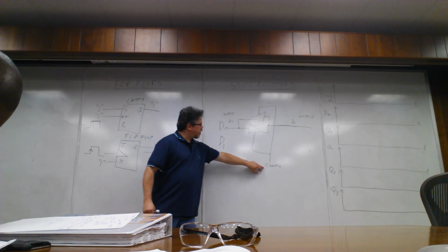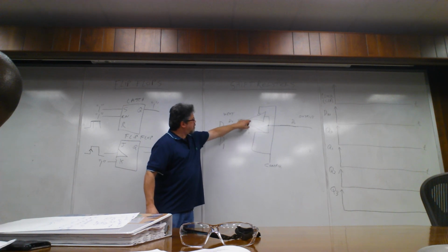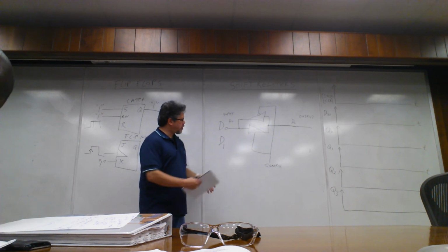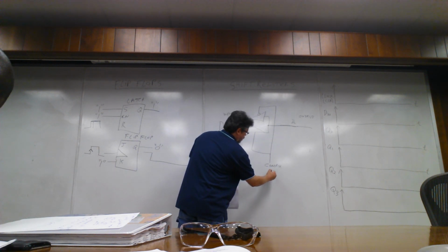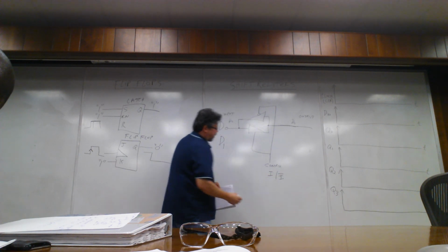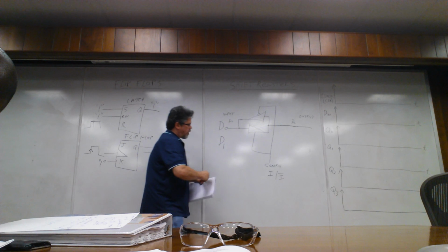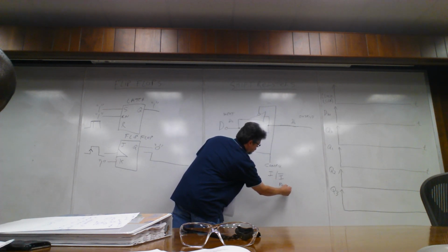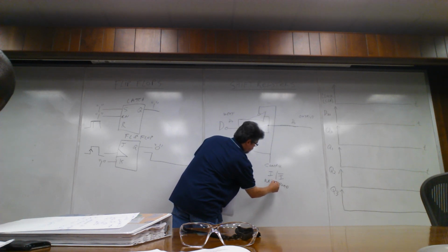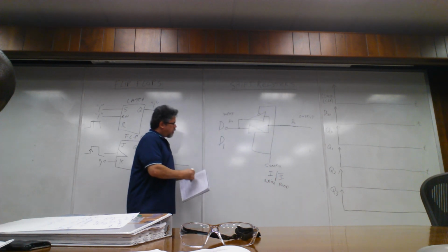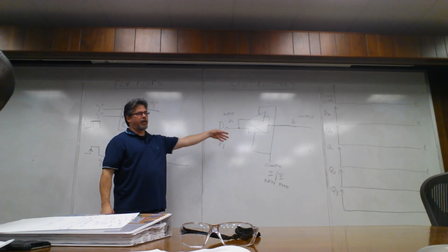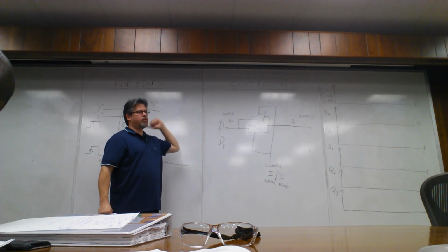So the micro has a control line, and it feeds a set of buffers. One buffer is enabled low, and the other one is enabled high. So depending on this control signal, it's either 1 or 1 not. It can steer it, and this might be a read operation, and this is write. So the micro basically raises or lowers that line, saying, I'm either going to send something out to memory, or I'm going to read something in from some switch out there.